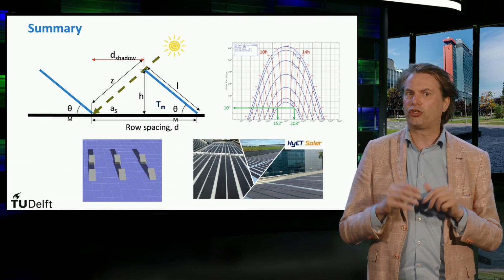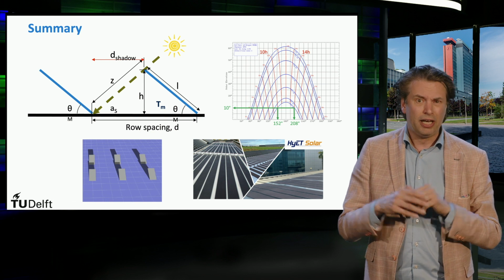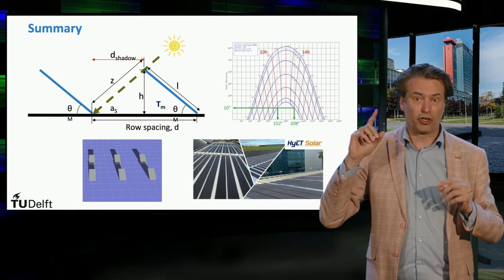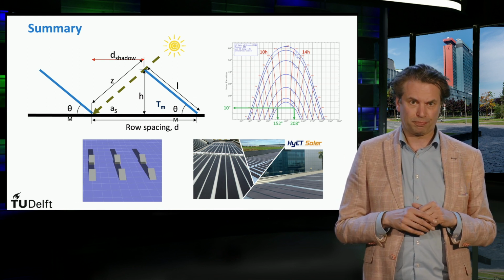However, we also have discussed that if new PV module technologies such as solar foil are considered as well, it becomes more important to compare PV system yield per functional area than using a metric like the module conversion efficiency.